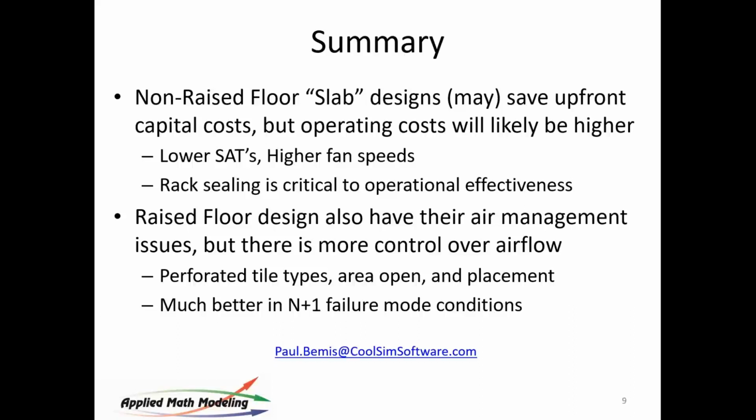Bill's asking, does IT equipment in the rack also have its own local fans? It certainly does. For regulating airflow, it certainly does. They have their own control system. And to be honest, none of us know exactly what those control systems are doing. The numbers I gave you of 100 CFM per kW is a rule of thumb that may not be valid.